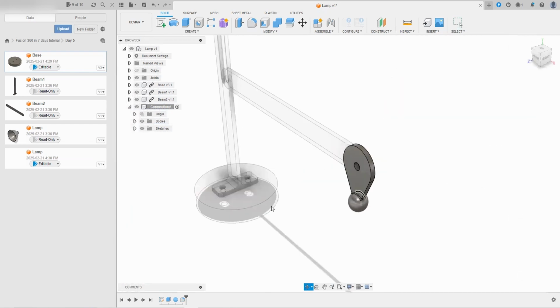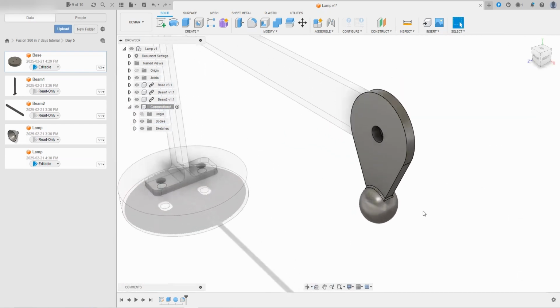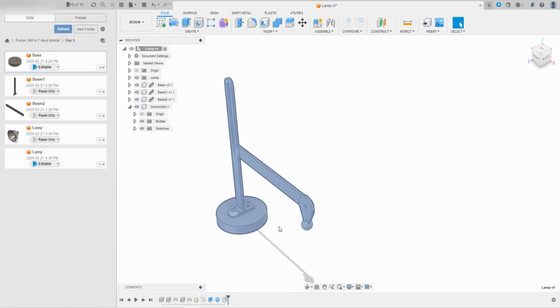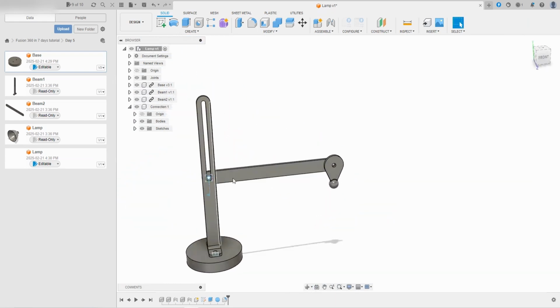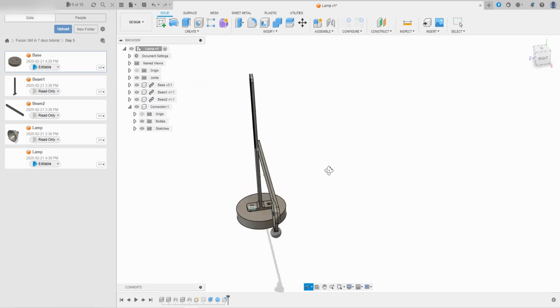And there you have it. We have created the connection joint directly inside the assembly design without altering the properties of the assembly's environment. To get back to the assembly, hover the mouse over the parent in the design tree and press on the circle that appears to select it. And as you can see, the rest of the assembly is no longer transparent, meaning that we are ready to create a joint between the assembly and the newly created component.